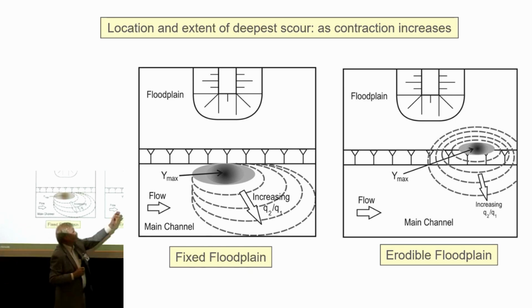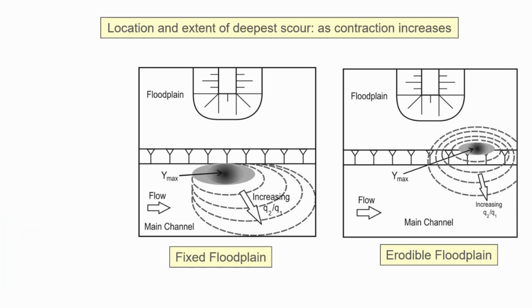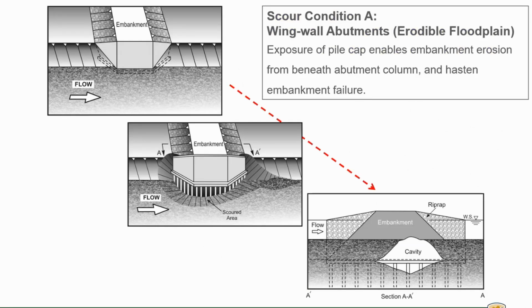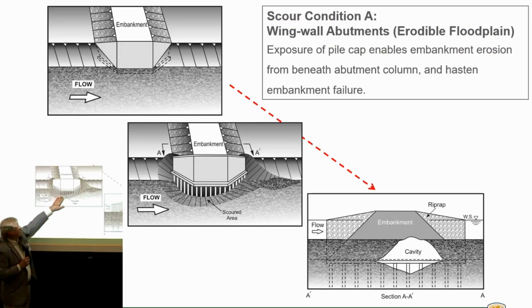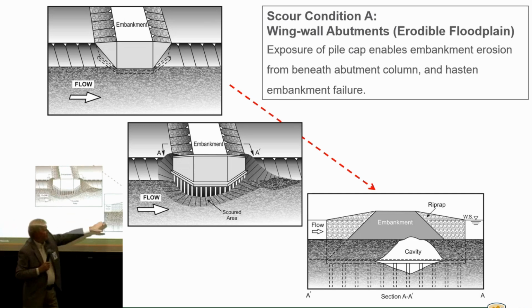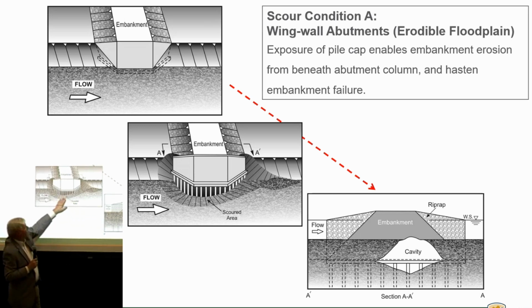Determining abutment scour is more a geotechnical problem, and you can estimate the scour depth from geotechnical considerations, slope stability considerations, than hydraulic considerations. It's too difficult hydraulically to estimate, in my opinion, the scour depth. Too many factors involved. Also for wing walls, you have to be very careful, because if you get erosion, you get geotechnical instability behind the wing wall abutment. The material will slough out below the abutment. If you have sheet piles, you can hold the material somewhat. Then you get breaching very quickly behind the wing wall abutment here.